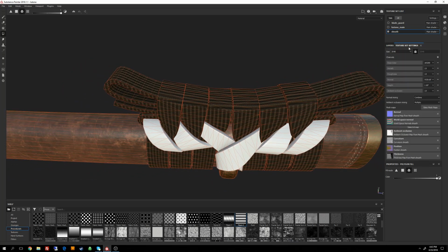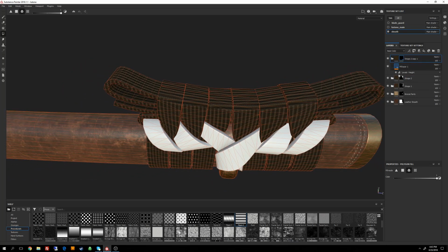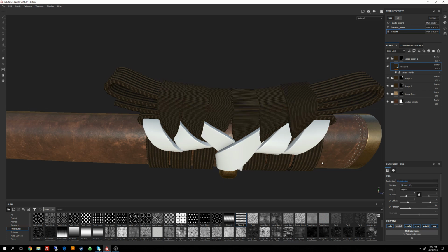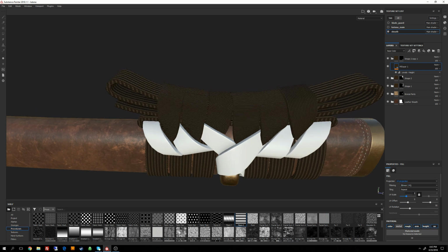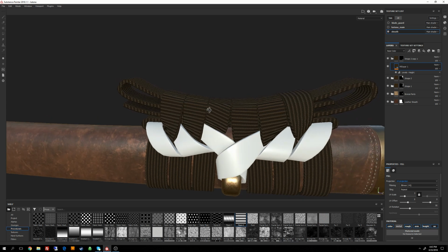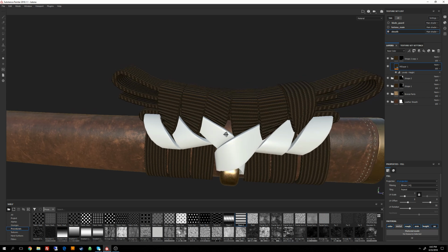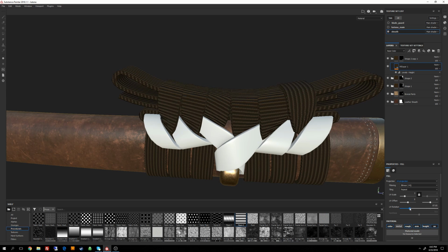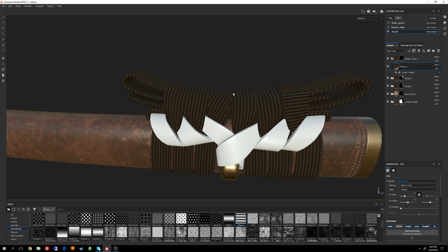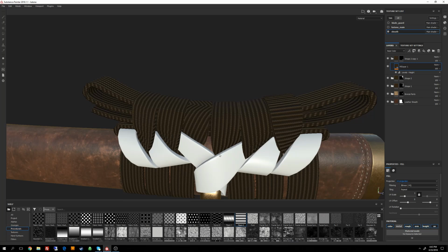So we're going to change our fill layer back to UV projection, and that changes the scale, so let's bring it back to 3. Okay, and it looks like some of these are going to work for us, but others aren't, so that one's a little more vertical. Let's try to see if we can address some of the ones that will work for us. So I'm going to, let's see, we probably need to drop our rotation back to 0. You can see that this piece and this piece work, but these two just aren't working very well, so we're going to have to address those pieces individually.